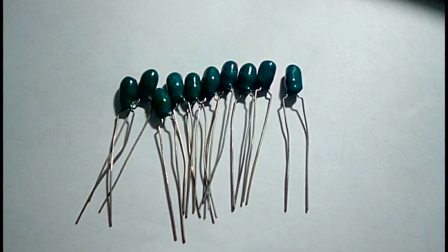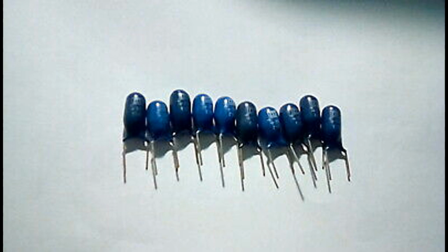Dielectric properties. Tantalum pentoxide has excellent dielectric properties, meaning it can store a large amount of electrical energy across a thin layer. The thinner the layer, the higher the capacitance, but it still needs to be strong enough to prevent breakdown under voltage. Uniform layer. The oxidation process ensures that the dielectric layer is uniform across the entire surface of the tantalum anode, which is critical for the capacitor's reliability and performance.